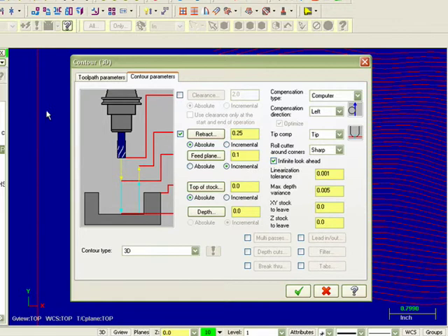And that's handy when you're doing something like cutting out a box. You draw a line that represents the boundary of the box, and you don't want to cut along that line, you want to cut outside it. And that would be when you're using this compensation. And you need to make sure you're aware of which way the vector is moving as you set that up. But since we're not using that, we're going to turn that off. And now these parameters are null and void.